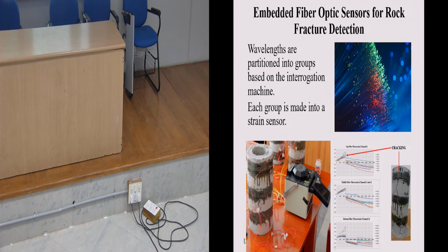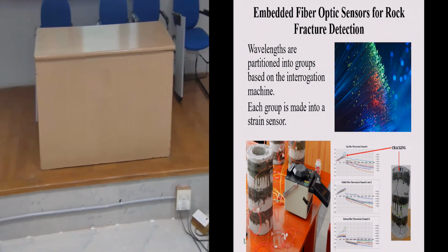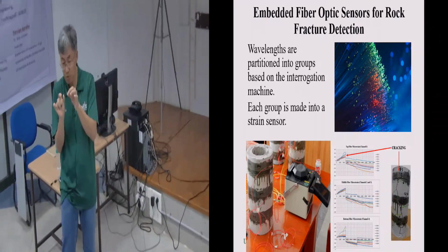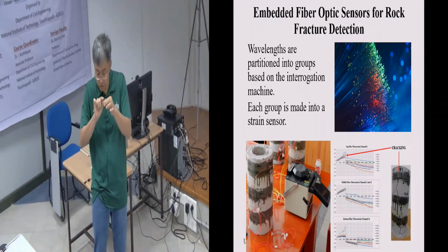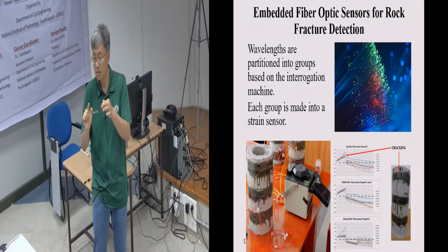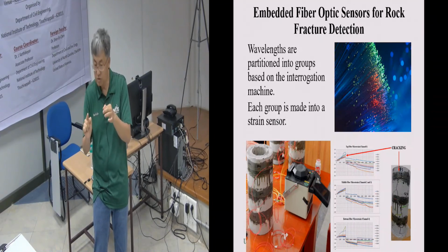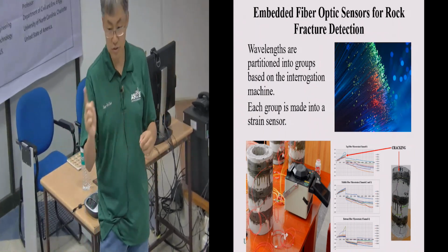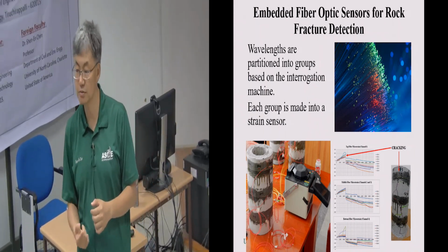But again, using this technique, the coupling becomes really important. I send my students to China to learn how to apply the strain gauge, because fiber optics are very fine, and the strain gauges are almost at the micro level. So you have to apply them in a very specific way using multiple coatings of epoxy. Those are things where you have to learn the skill set.